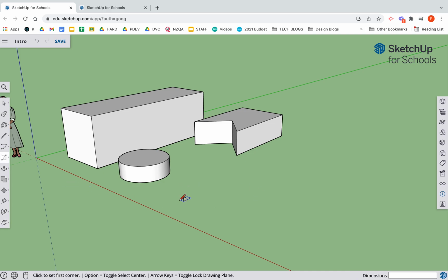One thing I definitely want you to do with your rectangle tool is to be entering in some different dimensions, using that comma in between. Don't drag your mouse around because it will change your dimensions. Just click once. So let me start again. Click once, drag in the direction in which you want your rectangle to be drawn. Let your mouse sit there, enter in some distances, and there we go. You get your form, and you are able to decide on how big it will be.